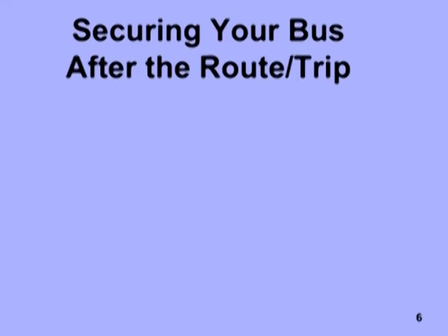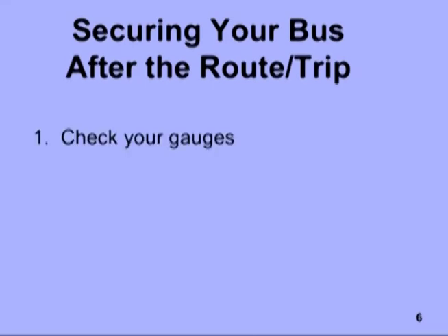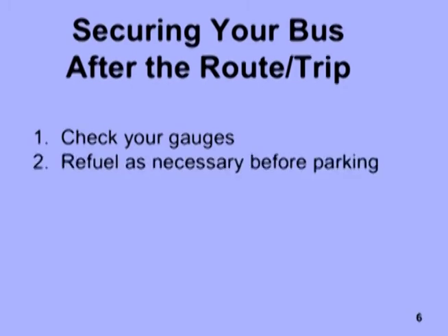At the completion of a route or your trip, always check your gauges to ensure that they are working properly and to determine if refueling is necessary. As a courtesy to your transportation supervisor and other drivers who may need to use your bus for a trip or routing, make sure you leave the tank at least 1/2 full of fuel.